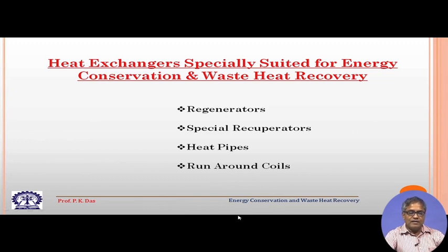First, let us say there is a hot stream. From that hot stream we need to extract a certain amount of heat. So, the hot stream is made to pass through some matrix or storage material. When the hot stream passes through the storage material, which is a solid material, the storage material will pick up thermal energy and then the cold stream will be made to pass through that storage material.